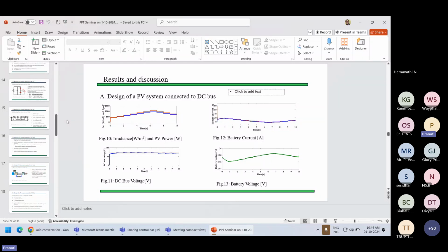You need to change the rules, and at that particular value, you need to import the .fis file and see what the parameters are. Okay, and what the overshoot and undershoot are, whatever you can plot and see, or whether it reaches the particular voltage level or not. You can see. And after the membership function, in Simulink we have to search for the fuzzy block for importing the .fis file.